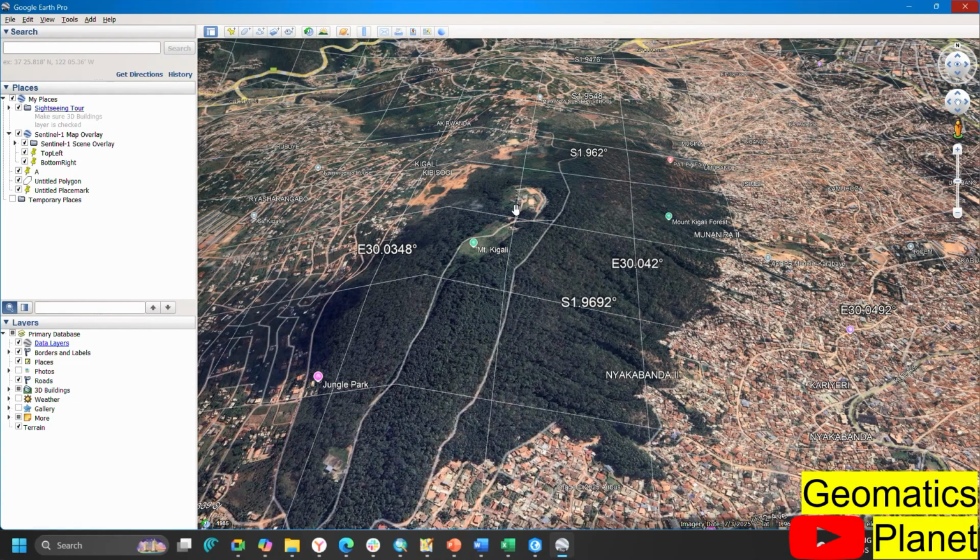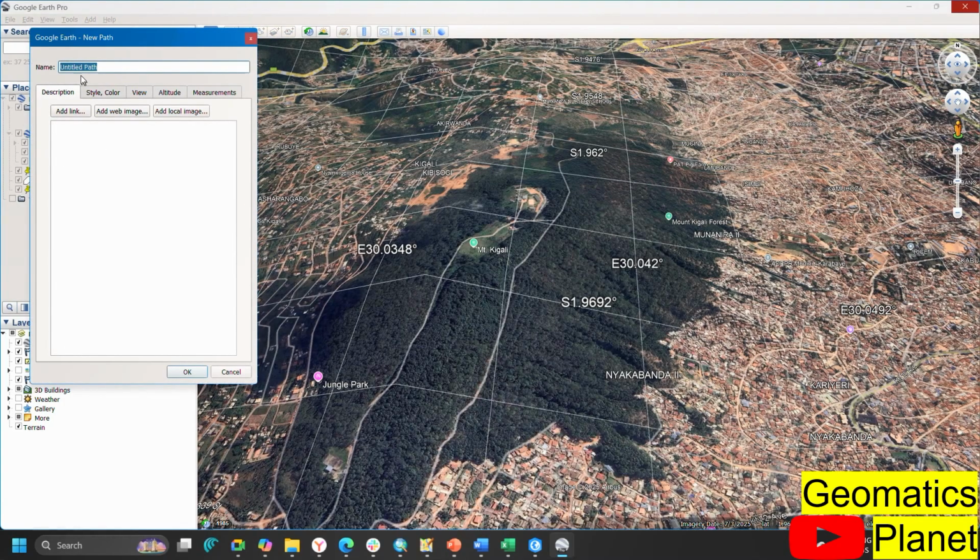So I see 6,000 feet. If I return here, it's 5,000, meaning there are almost 1,000 feet between the top of Mount Kigali and down here. If you want to visualize elevation, you can do that by using this particular key here. Here we have half part. We want to see elevation, so I'm just going to type elevation here, and then I will click OK.